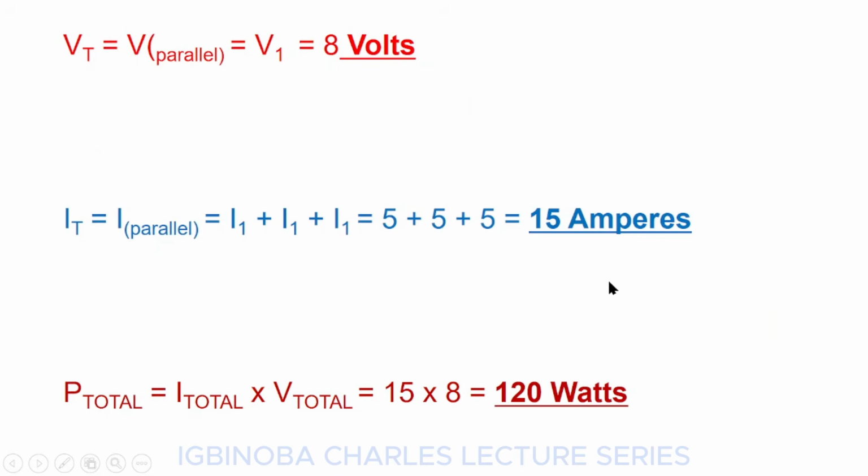You can see that the actual power is 120. That means it has been reduced to 63%. So in this case, you will discover that a lot of money has been wasted on the purchase of higher wattage panels when they are actually not doing anything in the system.